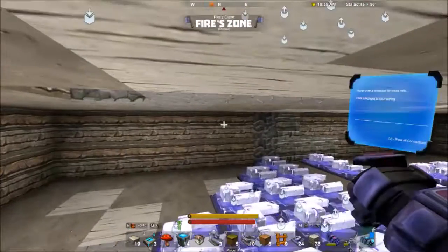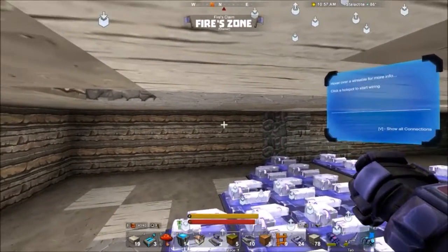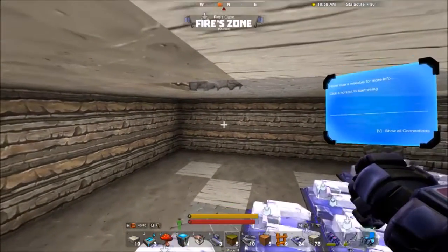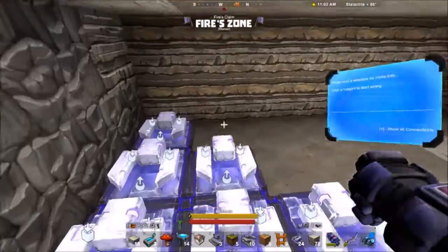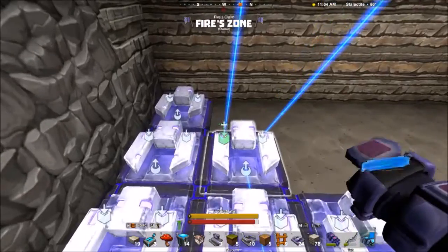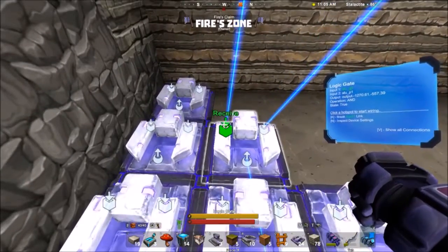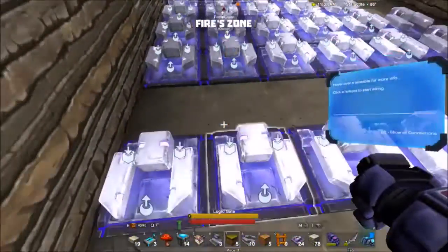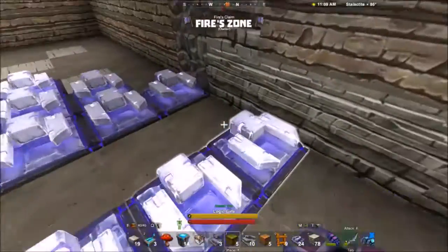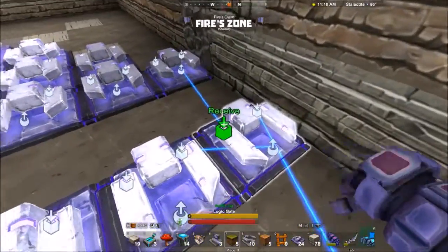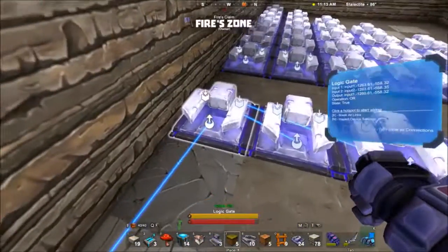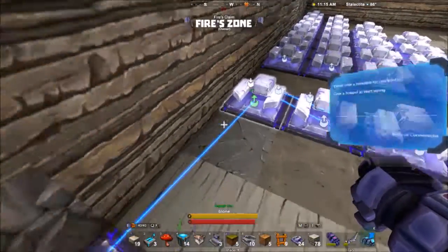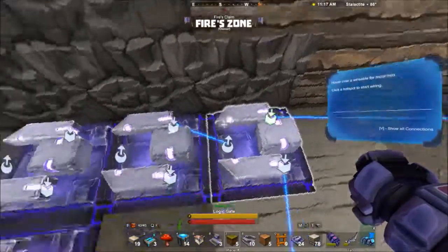Basically, if you generate at bit 1, bit 2 has to propagate it, or it's not going to go to bit 7 unless all of these are propagating. So that's why it has to be AND gates, because all of them have to propagate it for this to be true. And these are basically options, so all of these are just OR gates to get all the options. And that's it. The output comes here, and it comes as a carry.